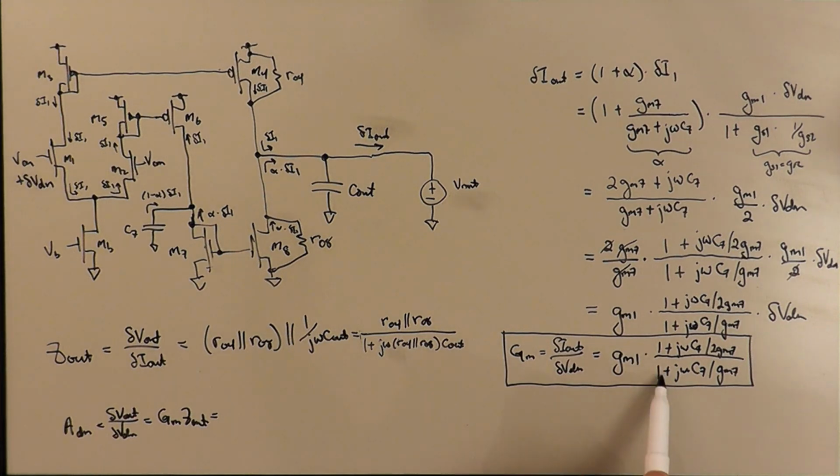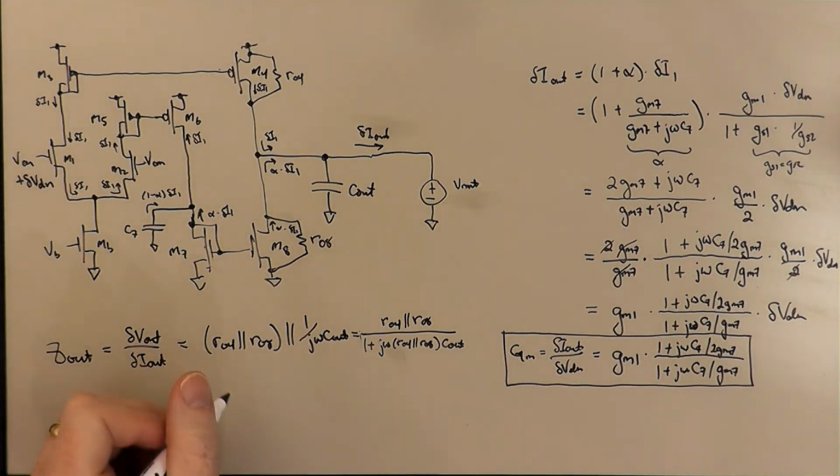And so by normalizing these polynomial factors to the constant term to unity, what that exposes is the prefactor is the low frequency behavior, and that's actually a very good way of expressing these things. It's a very nice way of doing so because a lot of times we maybe have already looked at the low frequency behavior, are interested in the low frequency behavior, and then we're interested in seeing how these capacitors or other impedances will shape the response as a function of frequency as we go to higher and higher frequencies. And so we would pick up here our normal low frequency gain, which was GM1